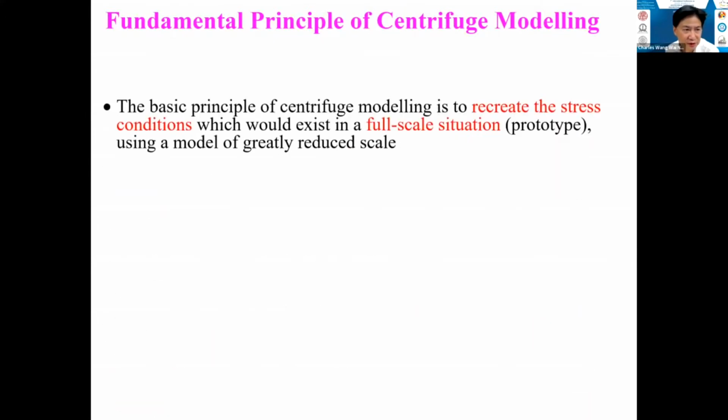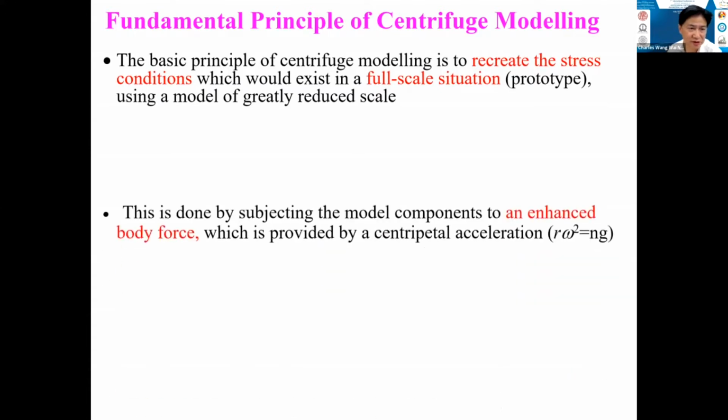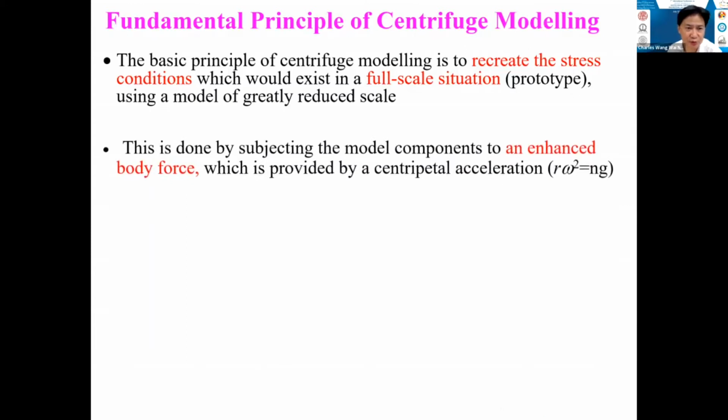So, what is geotechnical centrifuge modeling? Just in case you are not familiar with it, I will very briefly introduce it to you. The basic principle of geocentrifuge modeling is to recreate the stress conditions that will exist in a full scale, we call prototype, using a model of greatly reduced scale. And how can it be done? This is done by subjecting model components to enhanced body force, which is provided by a centripetal acceleration.